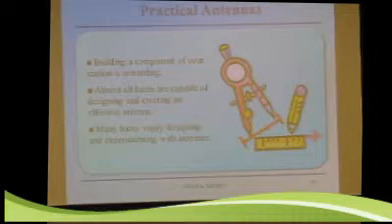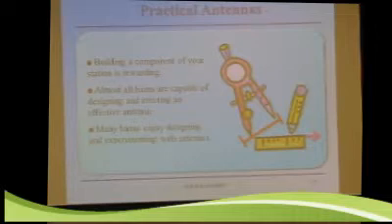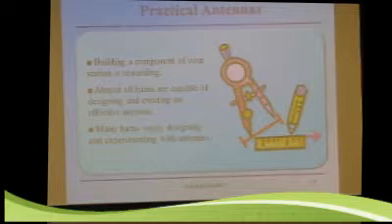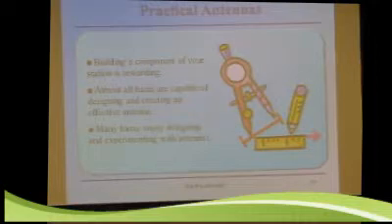And this was in the mid-70s when the CB craze was at its peak. So it got stolen, and I actually got it stolen a couple times. The insurance company was beginning to question whether they were really being stolen. But anyway, I found out these were 5/8 wave, that I could get a 19¼ inch piece of metal coat hanger, put it into an SO-239, and make a little antenna that would work. And I did, and it worked.